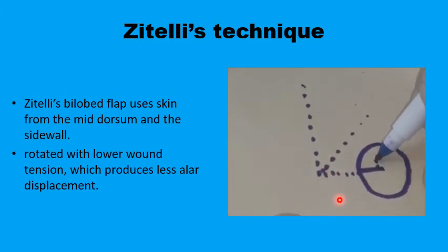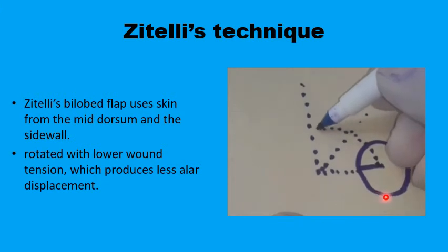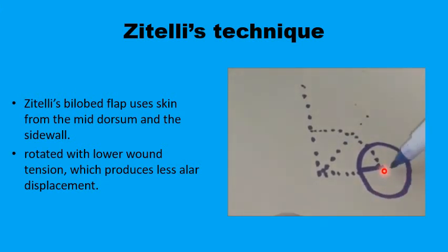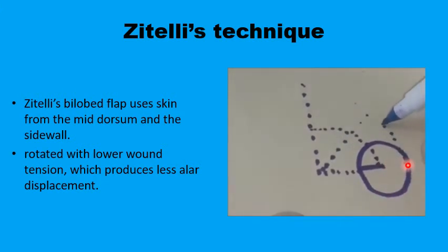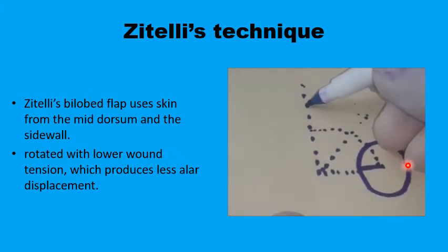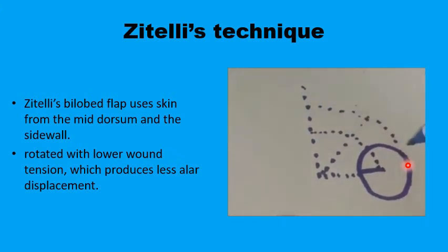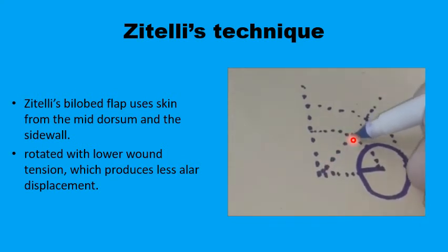And then you draw two arcs, the first from the center of the defect, the other from the circumference of the defect, and these two arcs would have a radius of twice the radius of the defect, or 3 times the radius of the defect for the outer arc.